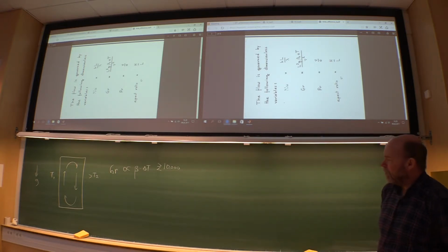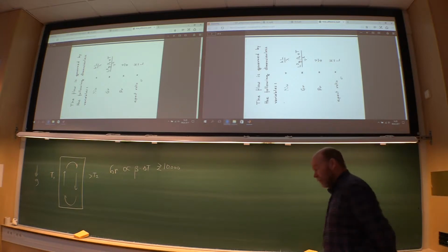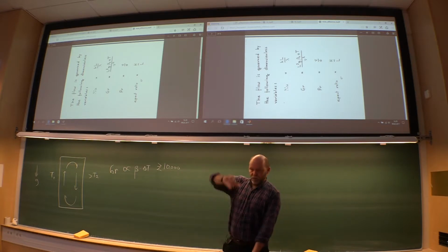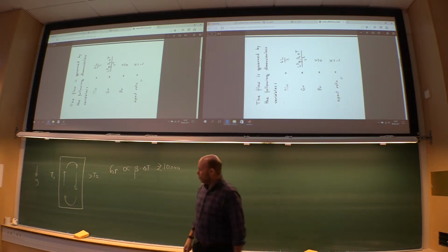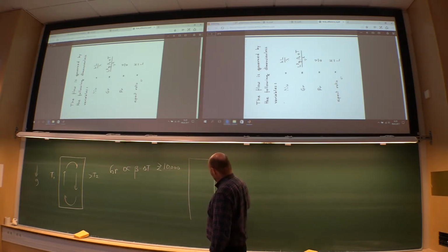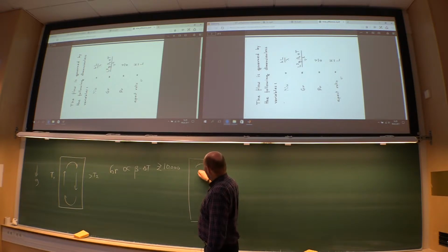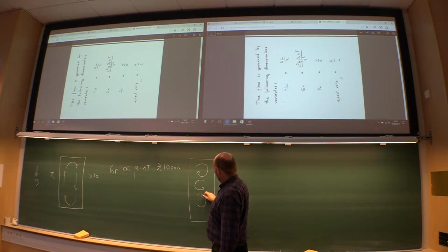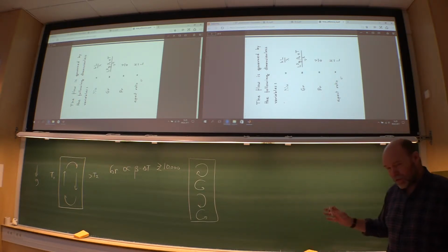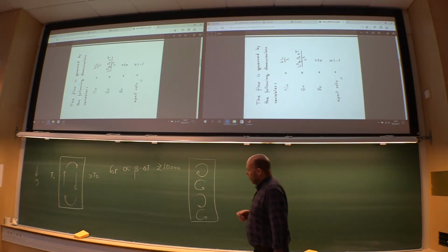And that's all. If the Grashof number becomes bigger than 10,000, then this large, narrow vortex is going to break up into many, many small ones. Then you will have the solution looking something like this. Vortex, and then a second the other way, and so on. So here you will have quite a different picture. A whole row of these vortices. It's not turbulence, it's still laminar, but these should be present.